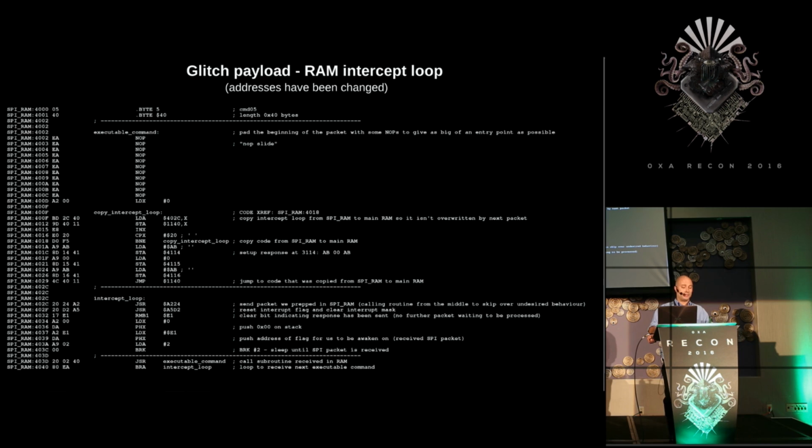There's multiple scenarios possible in addition to the one that I selected to target. Stack corruption is a possibility, and really any abnormal program flow has some possibility that it might eventually land in my code. So a von Neumann architecture without strong memory management is really fertile ground for glitching. Anything in RAM potentially could be executed.